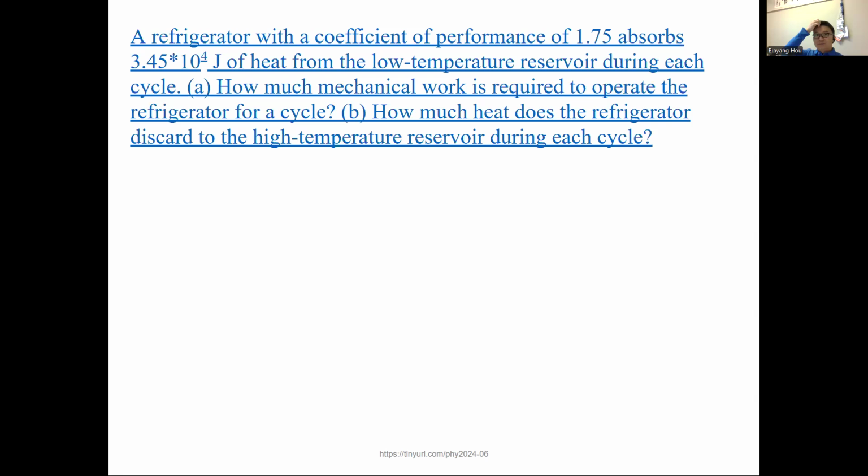It says a certain refrigerator with a coefficient of performance of 1.75 absorbs 3.45 times 10 to the fourth joules of heat from the low temperature reservoir during each cycle. How much mechanical work is required to operate the refrigerator for a cycle? And how much heat does the refrigerator discard to the higher temperature reservoir? So this is again looking for work and QH. It gives you QC because this heat is from the lower temperature, and then it gives you COP, the coefficient of performance.